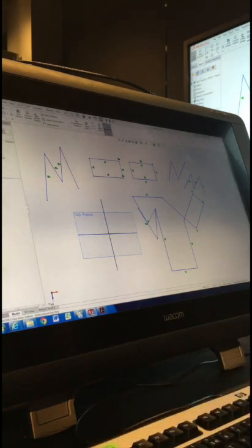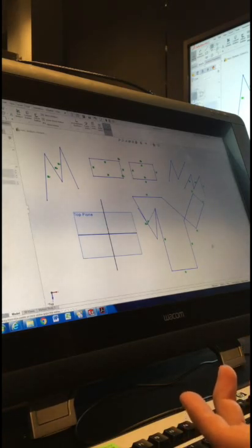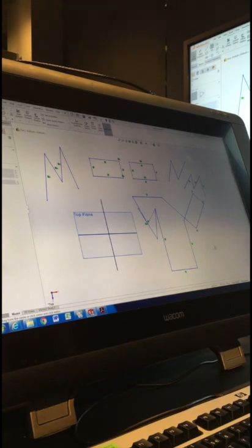All right, so let's change tools. So with the mouse gesture again, right click, drag, and drag to the right. And this time you'll get the circle tool. So with the circle tool, you basically click, one click, that starts the center point of the circle. You drag your cursor out, click again, that will drop the outside of the circle. So just add some different circles around. All right, and then that's done.